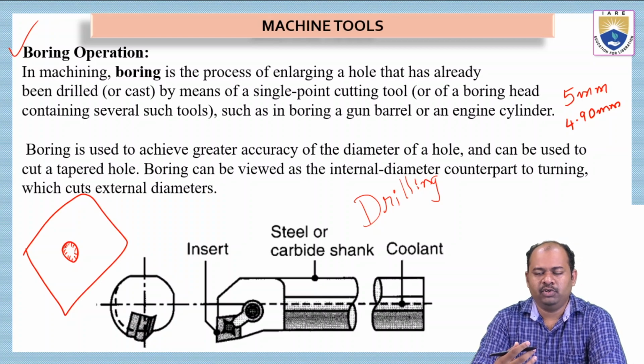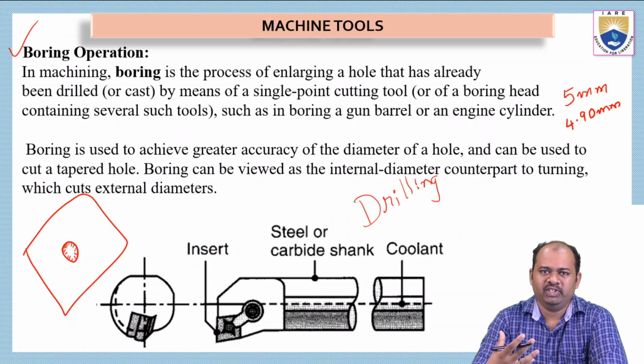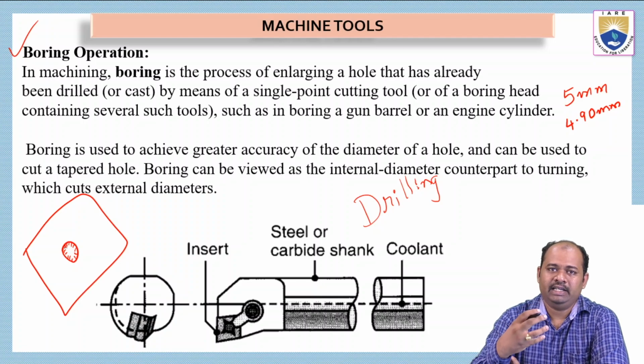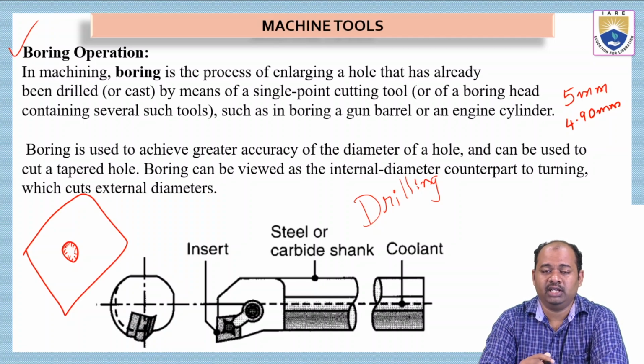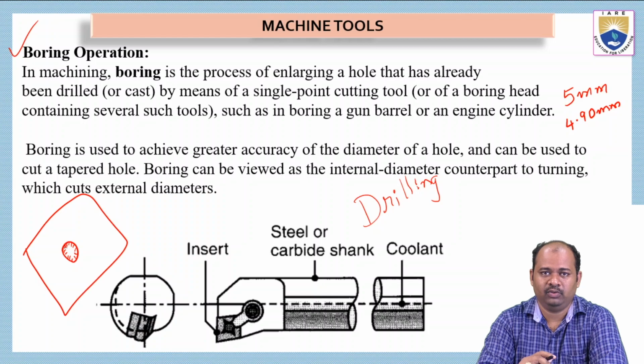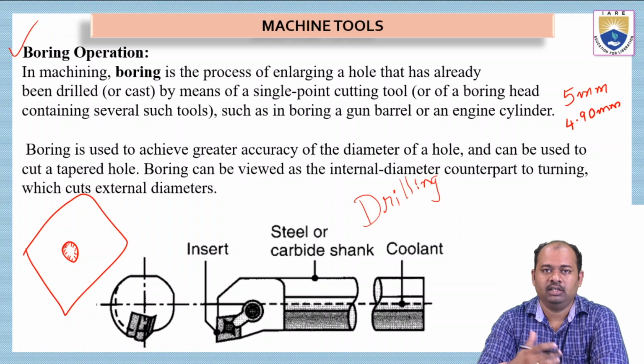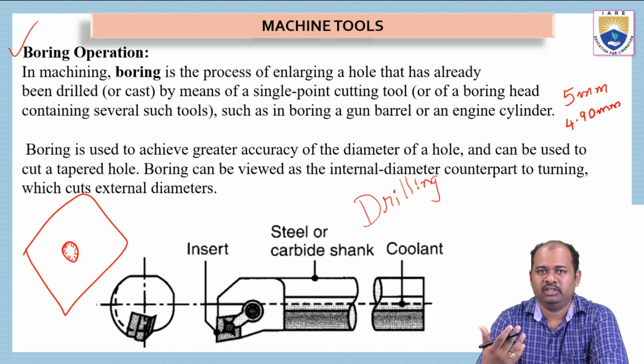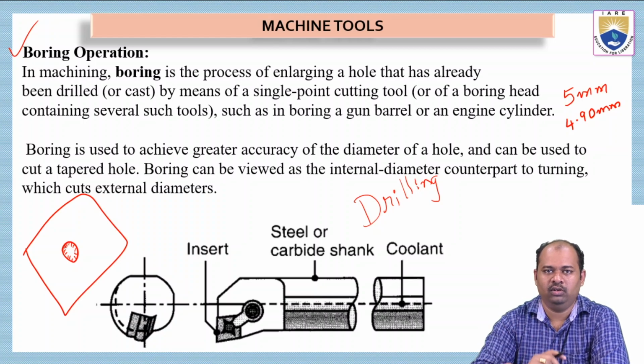Why does this happen? Because we are using a tool which is very hard and contains sharp edges which are very large in size. The drill bit cross section has very thick cutting surfaces, because of which we get a very rough surface inside the hole.